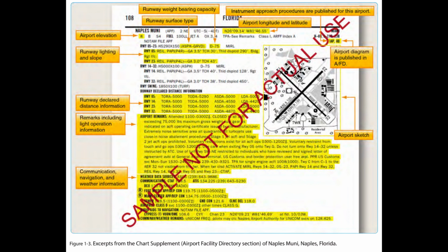their specific airport. All airport tenants are responsible for disseminating information to their employees and conducting training in low-visibility operating procedures. Anyone operating in conjunction with the SMGCS plan must have a copy of the low-visibility taxi route chart for their given airport, as these charts outline the taxi routes and other detailed information concerning low-visibility operations. These charts are available from private sources outside of the FAA. Government sources for SMGCS charts may be available in the future.